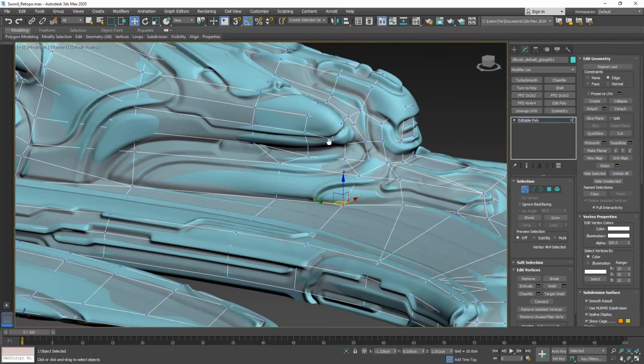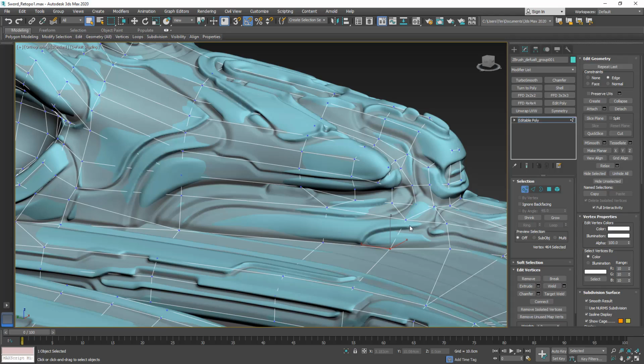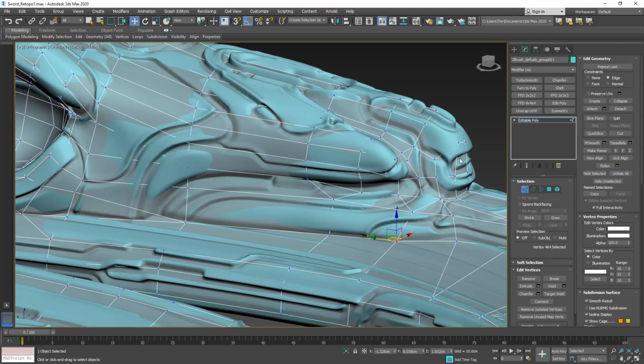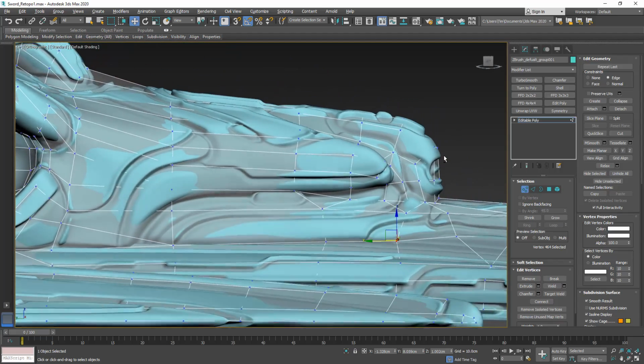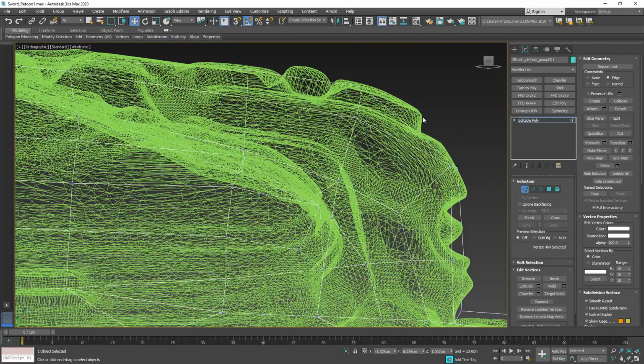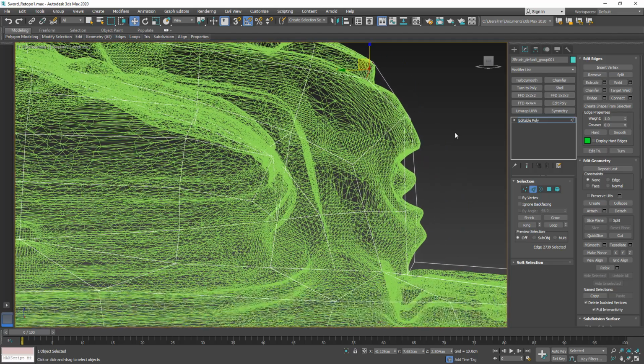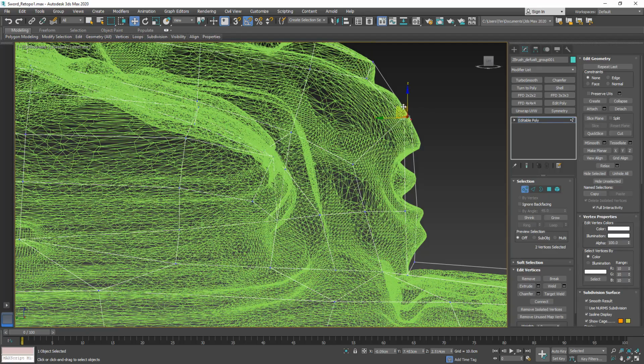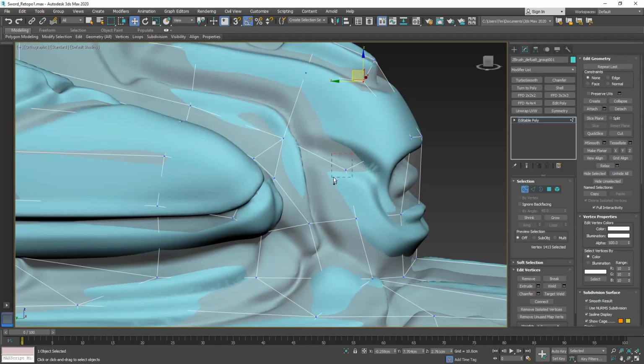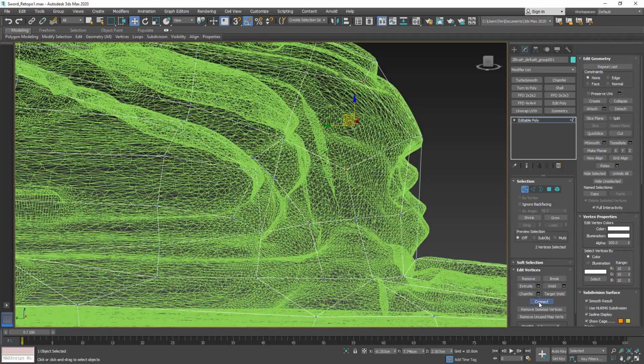Sometimes you just wanna jump in and out of the edge constraint mode in order to get the best results. Edge constraint will move it along the line, and if you're out of it, you can move it freely. Let's have another edge connection here, and in that case I actually want to be out of the edge constraint so that we can now have more of a curve there where we have this nose. I'm going to take these vertex points here and position them individually. Here we can make a connection.